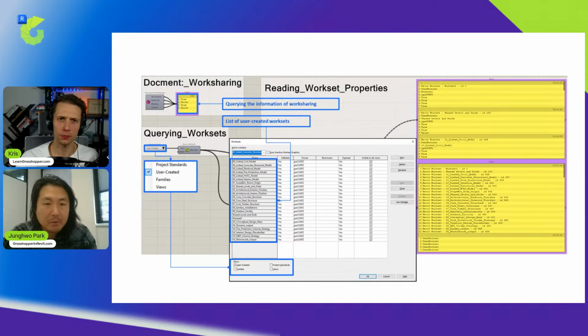Even one architectural model you may have to subdivide into different parts and zones. In this case, you need common worksets that work across all those domain models, and external partners or stakeholders' discipline models also need to keep the same worksets, which helps organize your model.